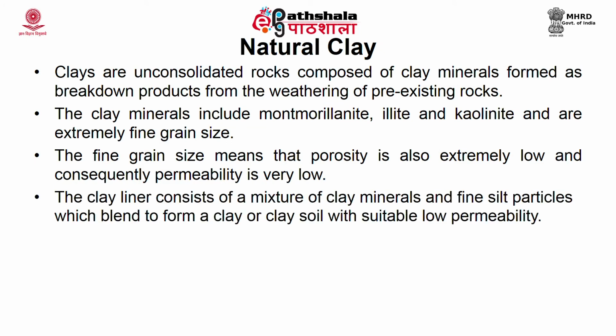So, how do you prepare a clay liner? The clay liner will be prepared by mixing these clay minerals with fine silt particles, which will be blended to form clay or clay soil, so that it will have a low permeability.